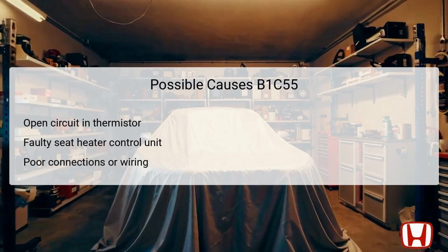When dealing with the DTC B1C55, several potential causes emerge that could lead to this specific error. One common reason is an open circuit within the thermistor itself, which may occur due to a break in the wiring or a fault within the component.